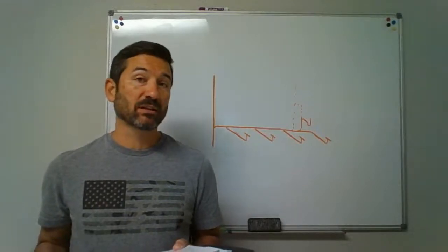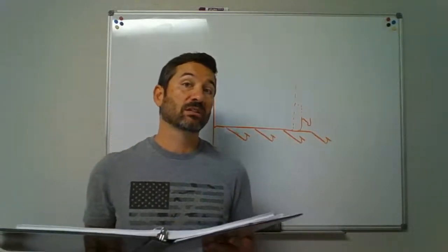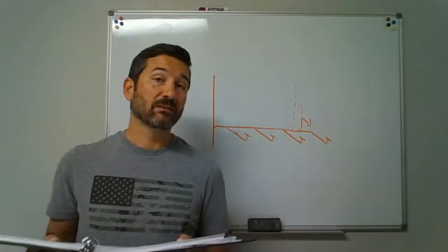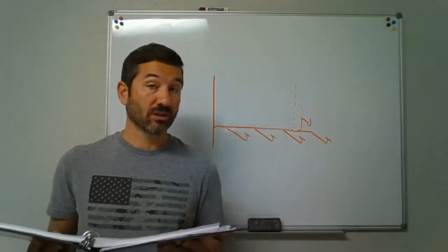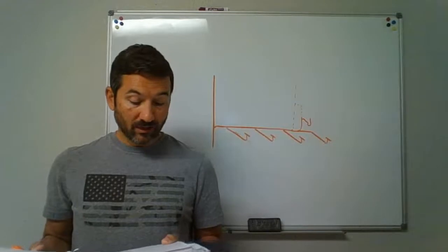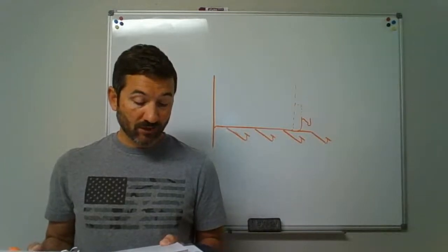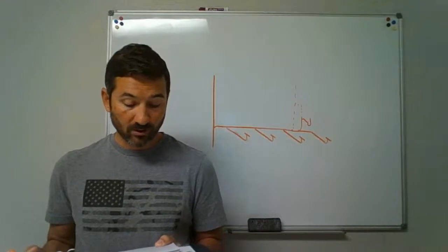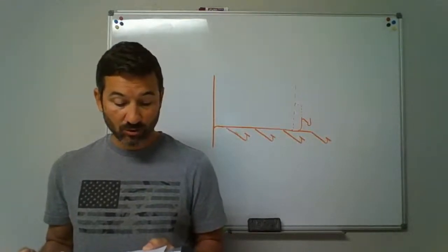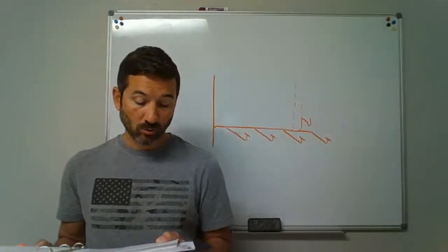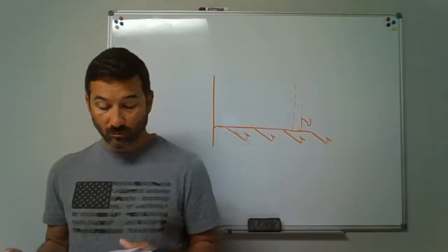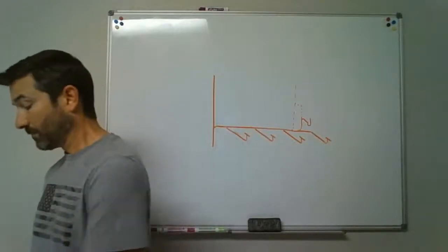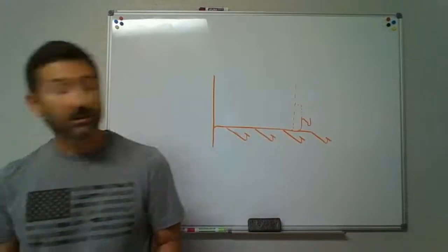We've already talked about a relief vent in other places, as far as a relief vent for the stack, but this is a relief vent when it's needed for circuit venting. The relief vent shall be provided for circuit vented horizontal branches receiving the discharge of 4 or more water closets and connecting to a drainage stack that receives discharge of soil or waste from upper horizontal branches. So there are 2 parts if you need a relief.